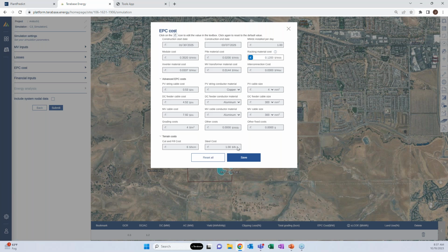Because we are calculating the pile reveal, we're using this in our steel calculation for cost. And I didn't point it out, but there's also a new user entry field in the racking definition, which is the embedment depth. So we're not doing the structural analysis of the piles. We're allowing the user to specify that embedment depth. So these things are combined in order to calculate an estimated steel cost.